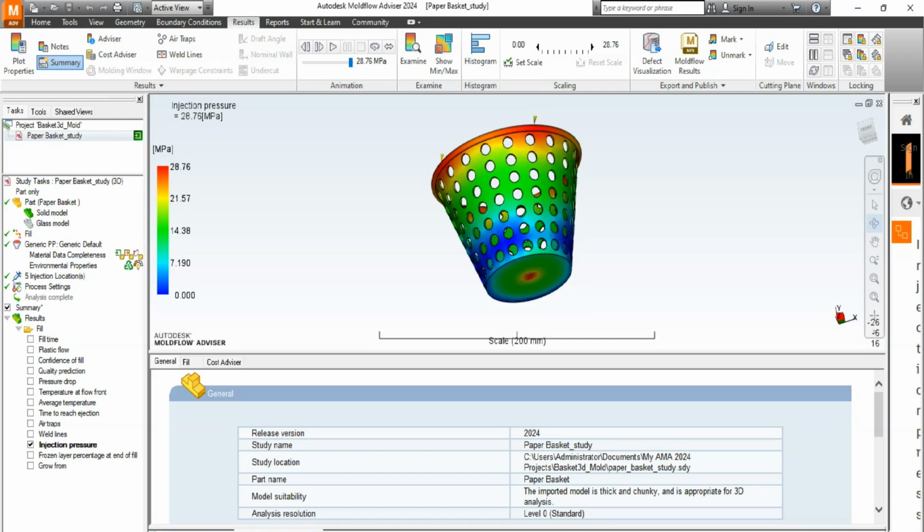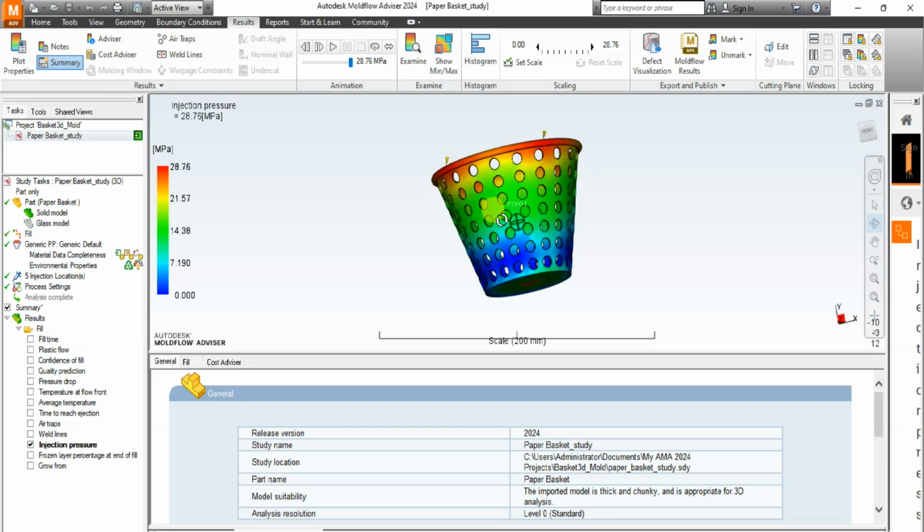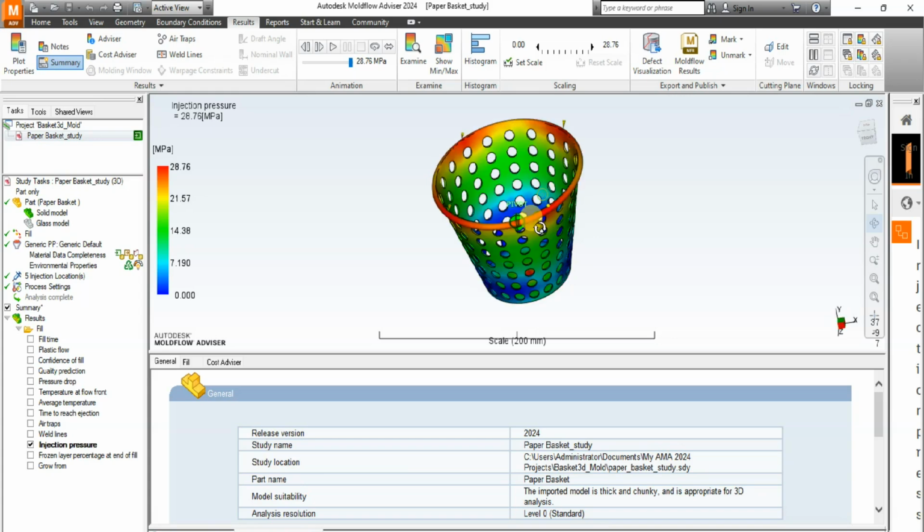The pressure at a specific location starts to increase only after the melt front reaches that location. So the pressure continues to increase as the melt front moves past, due to the increasing flow length between the specific location and the melt front. The pressure difference from one location to another is the force that pushes the polymer melt to flow during filling. The pressure gradient is the pressure difference divided by the distance between the two locations.